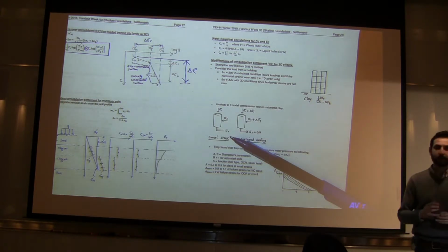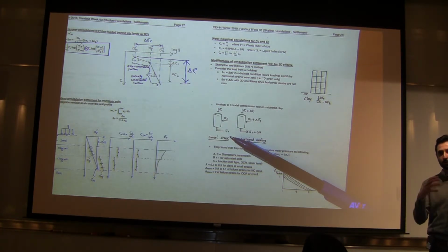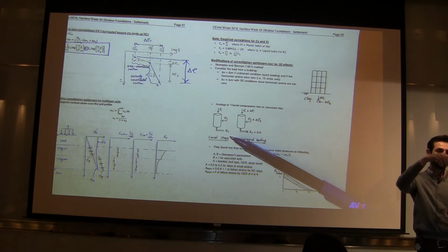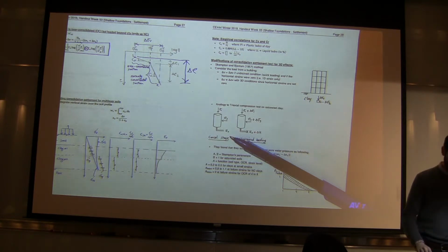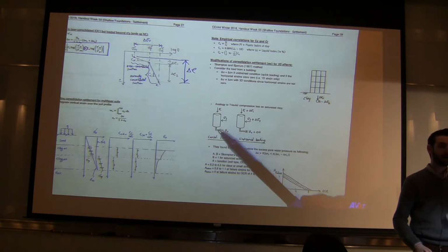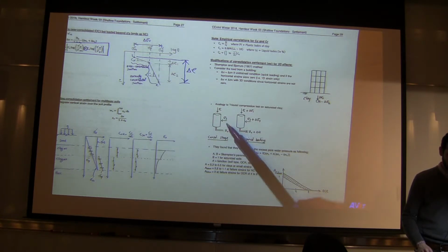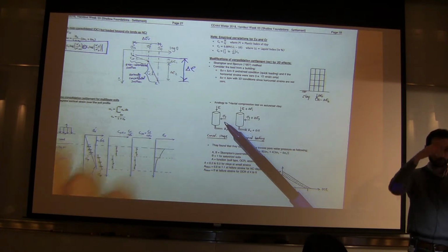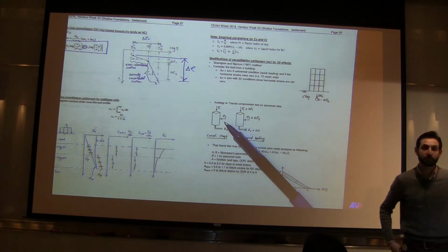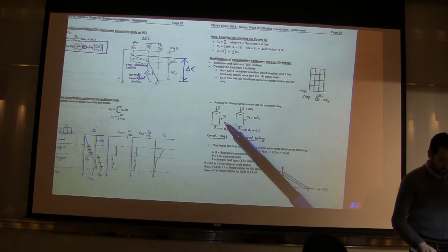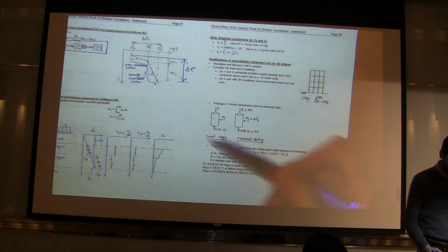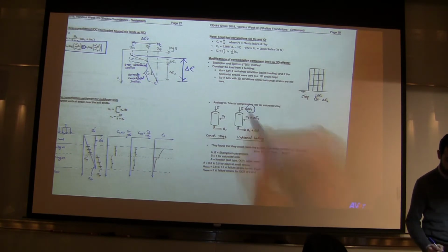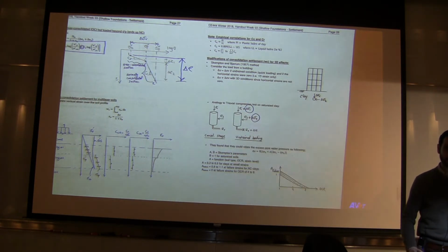And you remember in the triaxial test we said that the chamber pressure is equal, so sigma 1 and sigma 3 are equal around the sample, and then we increase the vertical load. This is now a very general case where you somehow have the ability to apply a different chamber pressure radially than the vertical pressure. And we have some triaxial devices that can do that. So that's before loading, and then after loading, you add some delta sigma 1 vertically and some delta sigma 3 radially, horizontally.